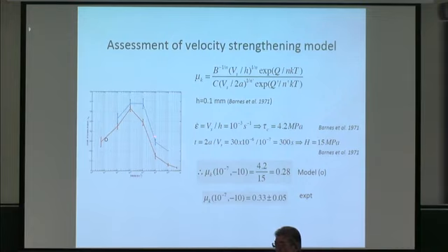Whatever, it's the lower range on our sliding speed, and ask, what does the model predict about the coefficient of friction under that specific sliding speed at minus 10 centigrade? And if you put some parameters to work and take as the deformation zone 100 micrometers, as Barnes, Tabor, and Walker taught us, then you end up with an expression that says, okay, at 10 to the minus 7 per second, the model, we have the shear strength of 4.2 megapascals, the hardness taking for their 300 seconds of about 15 megapascals, a coefficient of 0.28. That's the 0 here. The measurement under those conditions is 0.33 plus or minus 0.05. You say that's not bad.